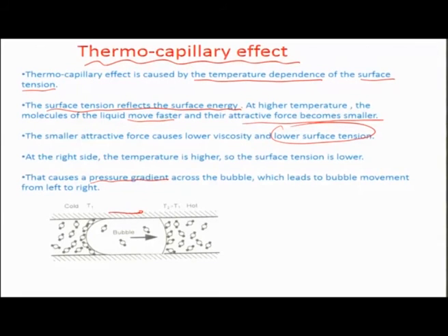So, when we talk about such microvalves, there are many actuation schemes which are available. You saw that there is a thermocapillary effect, an electrostatic capillary wetting effect, a thermopneumatic or pneumatic effect, and then the electrochemical effect, and these are all different ways of performing actuation for which suitable designs can be initiated to do this basic phenomenon of valving. So, I think I have gone through some of the very critical aspects of microvalving.